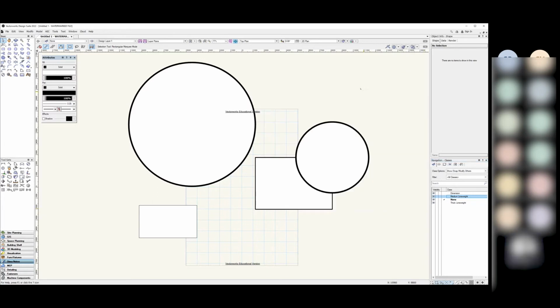So I'm going to try something different this time. At the moment, I've still got my none class selected. I've still got a little tick next to it. And if I were to try and make a shape again at the moment, it's going to apply my none class, which is kind of rubbish. If I double click on my thick line weight class, you see it's now got a little tick next to it.